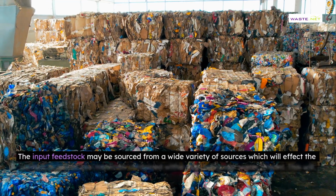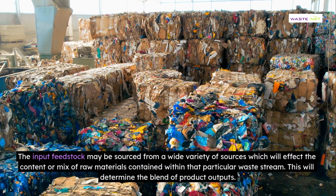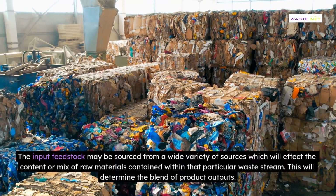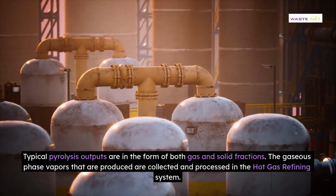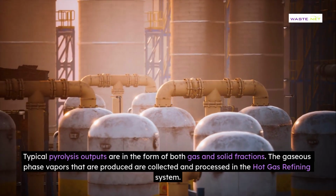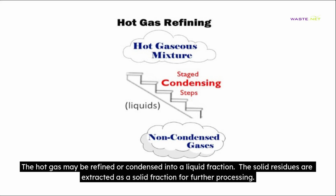The input feedstock may be sourced from a wide variety of sources which will affect the content or mix of raw materials contained within that particular waste stream. This will determine the blend of product outputs. Typical pyrolysis outputs are in the form of both gas and solid fractions. The gaseous phase vapors that are produced are collected and processed in the hot gas refining system. The hot gas may be refined or condensed into a liquid fraction. The solid residues are extracted as a solid fraction for further processing.